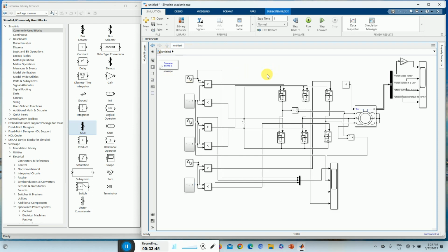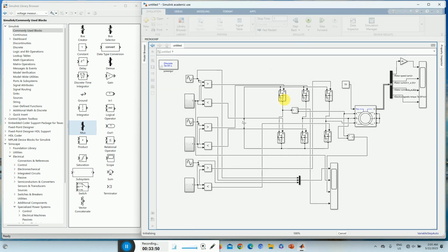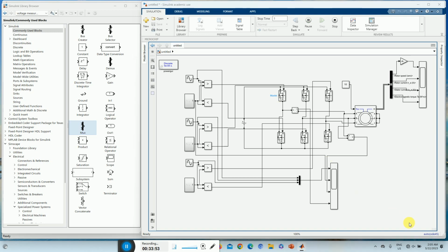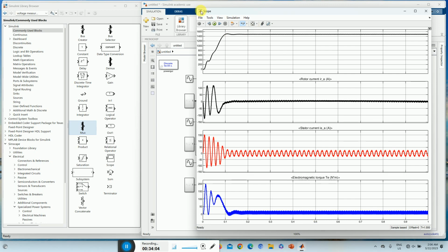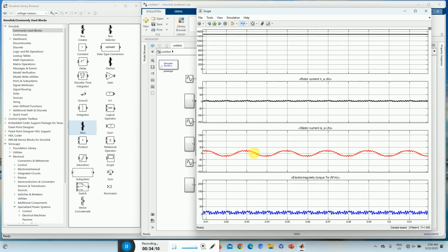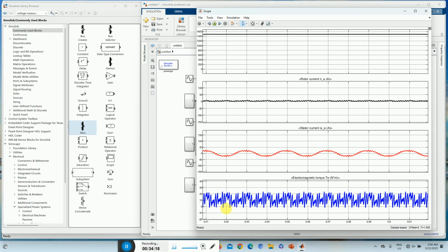Now the switching frequency is very high, 21 times. How do the speed torque characteristics look? Now if I run it, oh, you can see that this ripple has reduced a lot, right? The rotor current gets smooth, and the stator current is smoothened up. Torque ripple decreases a lot. Previously it was oscillating a lot in the negative range, and now it is from 0 to 20 only.